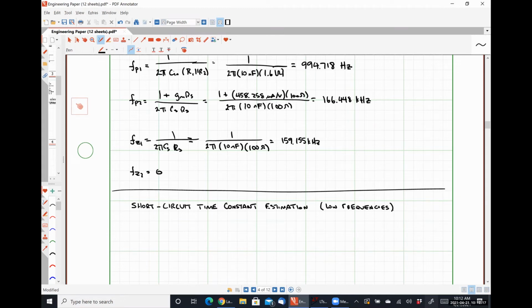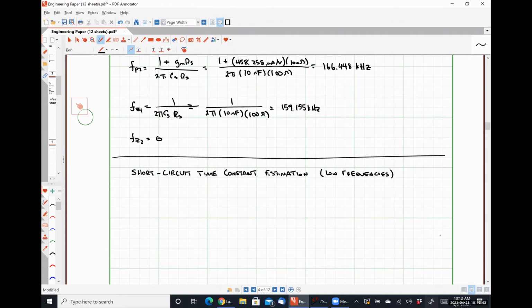The short circuit time constant estimation in principle just says that we are going to be looking at our circuit with only one capacitor on and our input turned off, and seeing effectively what resistance each capacitor sees, to develop a time constant for each capacitor. Okay. I know that sounds like a bit of gobbledygook, but it'll be a little bit easier to understand in a moment. Ultimately, we will find that an estimation of omega low can be given if we do the following operation.